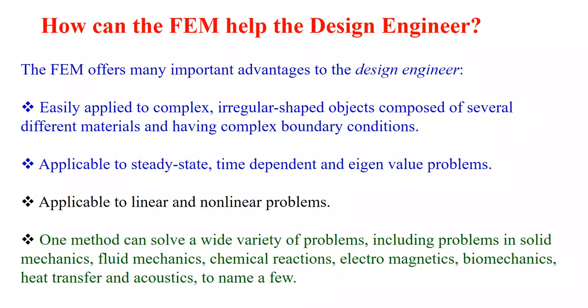The second one: FEM is applicable to different conditions, such as steady state conditions, time dependency and eigenvalue problems. Steady state conditions, without time dependency, apply to static structures, and with time dependency, objects in dynamic motion can also be solved.